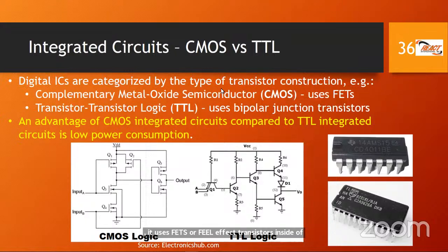Also CMOS, by the way, are very sensitive to static electricity. So when you're handling CMOS, any type of CMOS at all, you have to be very careful that you don't zap it, so you have to ground yourself off, maybe use an anti-static mat, and so on, right? So that's one of the differences, right? Just for your information, they need to be handled very, very carefully.